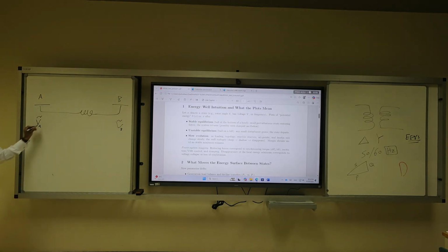So what is the VA phasor? It is a magnitude times e to the power j of an angle, call it delta, and delta is in radians. In your Python, you denote the VA phasor with VA as a real number, it could be 100 kilovolts, times e to the power j of an angle.